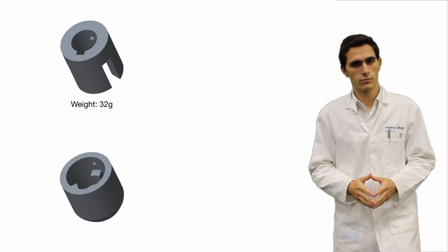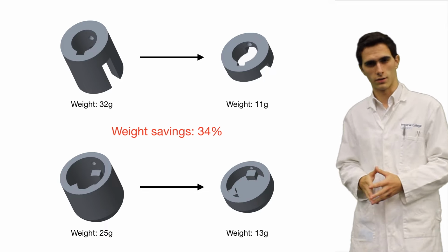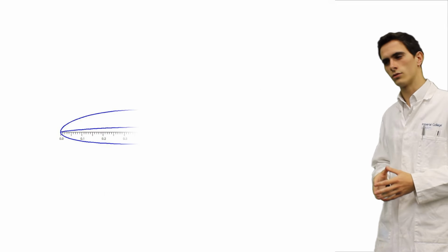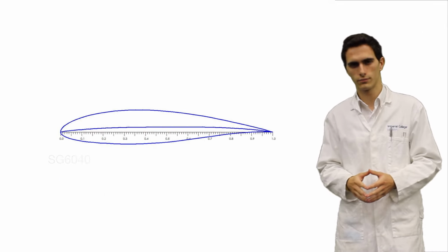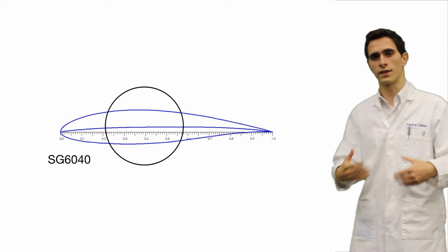To reduce the mass, both the hub and the cone can be made shorter and thinner. Another important element to minimize is drag. To do so, the cross-section area of the wood can be reduced, and a circular wood can be used instead of the airfoil one, such that it acts more as a bluff body.